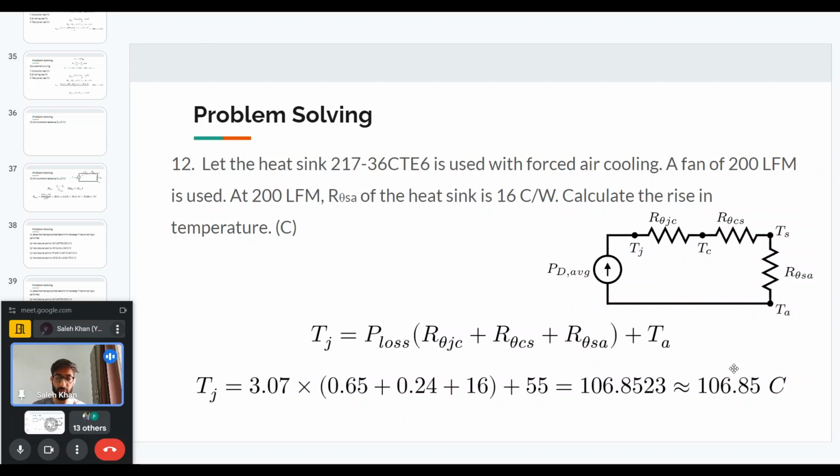So that will also lead to higher cost. That is why we want to find a thermal heat sink which is just enough to let us operate the device in a safe manner, but without increasing the cost too much. That is why we are doing all these analyses, to approximate as closely as possible the power loss and then find the heat sink that we can use.